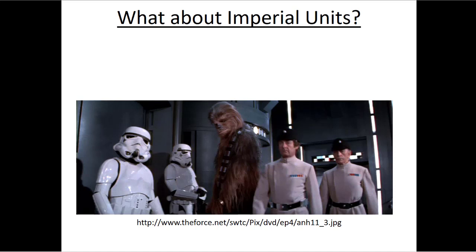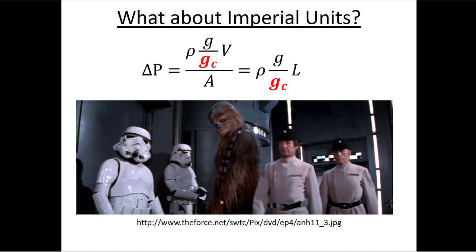Now, of course, everything's always more difficult with imperial units. And in that case, anytime in an equation you see g, your spidey sense should start tingling, right? The hairs on the back of your neck should stand up, and really that g then gets replaced by g over gc because it's not acceleration of gravity, it's the relative acceleration of gravity because pounds are pounds here on Earth.